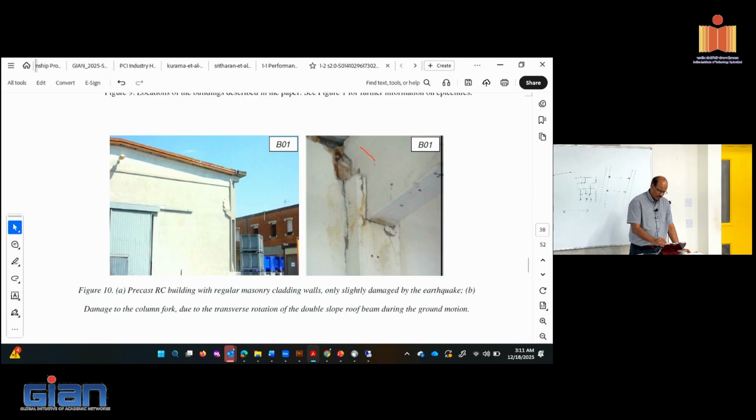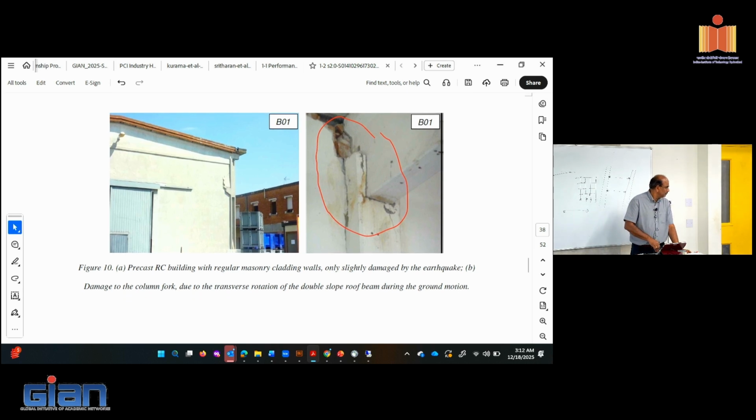So here's another example. So this is where the precast would come in. You could see all of the damage would occur just in the connection region, not in the precast member. Whereas if you go back to the regular cast-in-place, the reinforcement is continuous, and the weak region or the critical region becomes plastified. When that happens, the member is continuous, the connection is not separate or added on, so therefore the performance appears to be better, even though locally it has gone through some distress and crushing and spalling of concrete. We'll look at some of the examples.